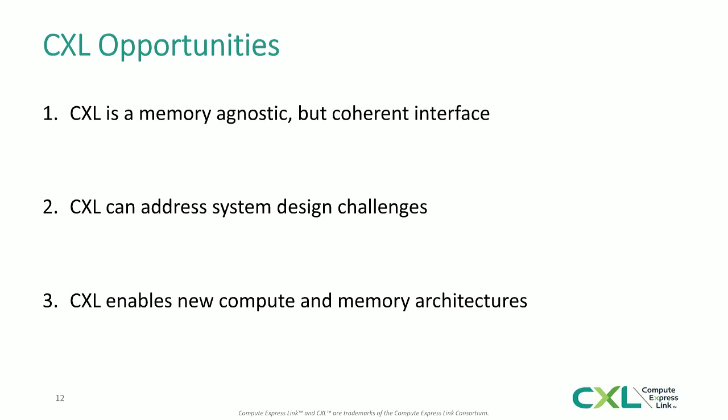Thank you, Prakash. So overall, CXL provides us with a number of opportunities to help address some of these challenges. CXL is a memory agnostic and coherent interface. In this context, when I say coherent, what I mean specifically is that we're able to map the underlying memory devices into the system address space so that we can do loads and stores directly to that memory device. The other area this helps us address is some of the specific system challenges that Prakash walked us through earlier, and I'll get into more detail on how we can do that in just a minute.